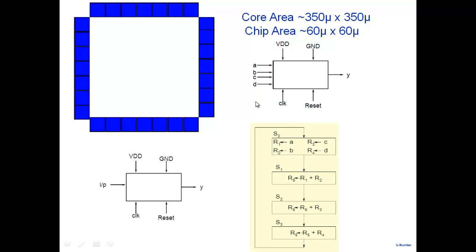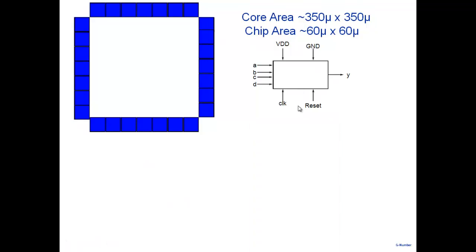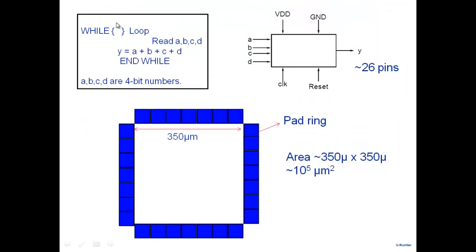Okay. So the design, from the description which is given, does not go like: I start from here, then I do RTL, then I do gates, and then I implement each gate and do a final chip design. At this stage itself, one starts to think about what my final IC would look like. So one starts looking at the different blocks that are there and how they will fit into the area that I have. And that may have an impact on how you are conceptualizing the RTL design. The choices that you're making here, do they make sense?